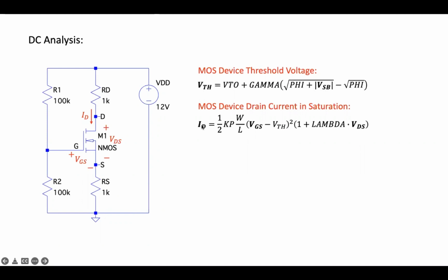So it turns out drain current has 3 input voltages, no? Although VGS has the dominant effect. So aside from the dominant VGS, drain current is also affected by VDS due to the channel length modulation and by the VSB due to the body effect. Okay, is that principle clear?